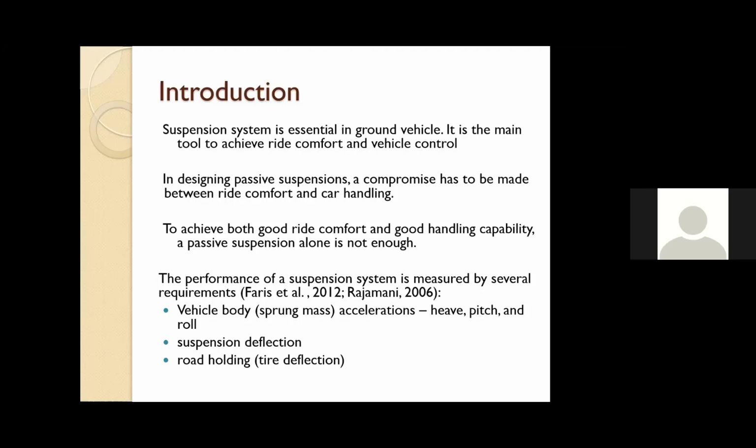We are going to check three main criteria, in fact, for this. When we talk about ride comfort, we talk about the acceleration, different types of acceleration according to the body movement of the car: heave, pitch, and roll. Many people will focus on heave only, and yes, it is one of the major measures, but in fact, pitch and roll also are quite important as well.